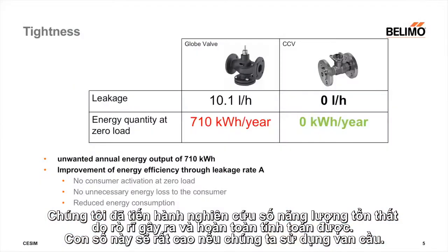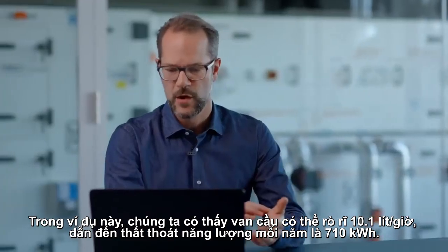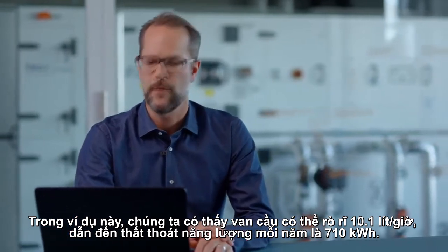As we have already learned about energy efficiency from another SESIM module, this energy loss of a globe valve can be calculated, and it can be quite high. In this example, we have a leakage rate of this globe valve of 10.1 liters per hour, which leads to an energy quantity at zero load every year of 710 kilowatt hours.